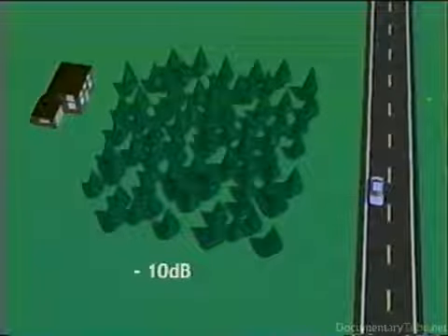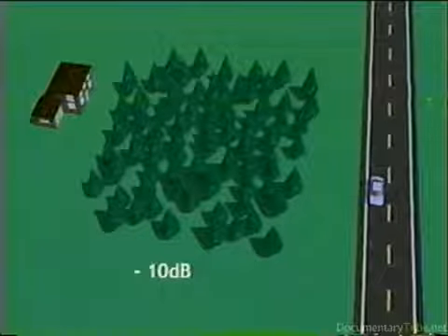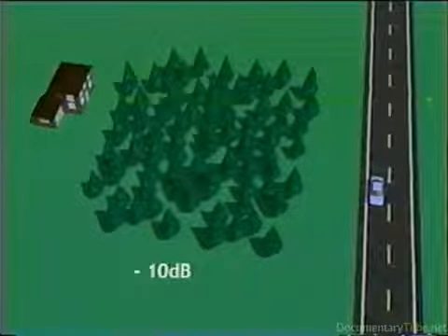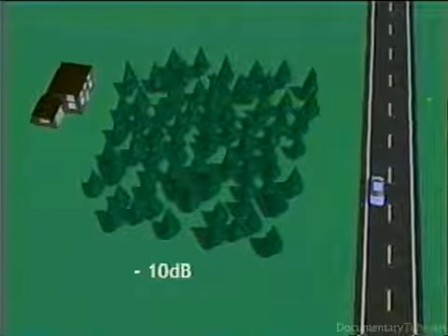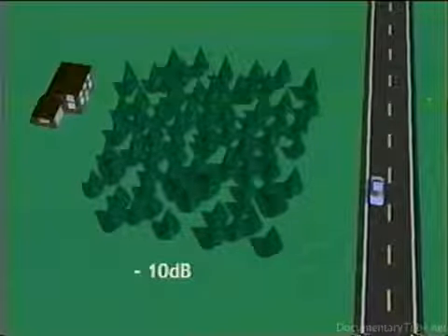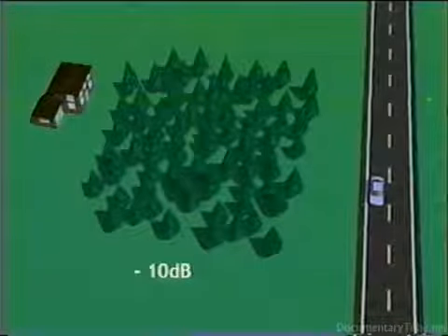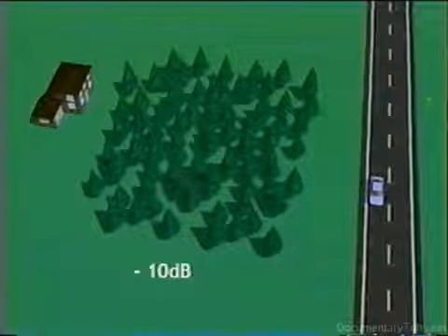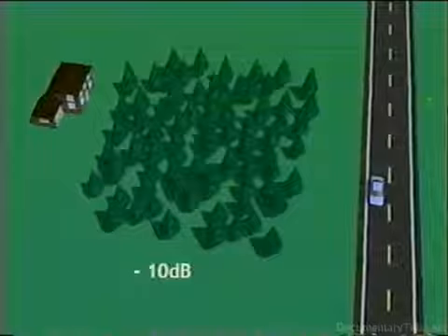Theoretically, using foliage to reduce the noise in communities surrounding highways is appealing. However, foliage of sufficient width and density to reduce noise is not usually found along highways. Vegetation planted as part of a highway project will not provide noise abatement.